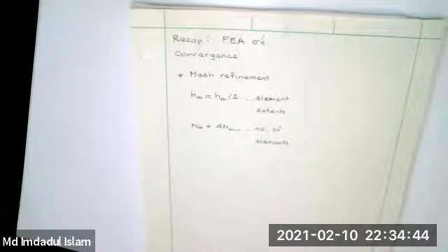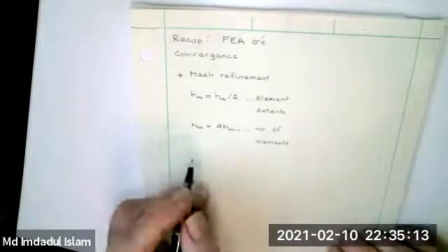is we take element extents and we halve them. Now, the element extent size varies throughout the mesh, but if it's 1 in one place and 4 in another place, then it goes to half in the first place and 2 in the second place. So you do this for the average element size. What will happen then is the number of elements will quadruple in 2D, and that's what the focus is here. Once you've done that, you're going to have results, and you need results from 3 meshes, and then you can check for your convergence requirements.